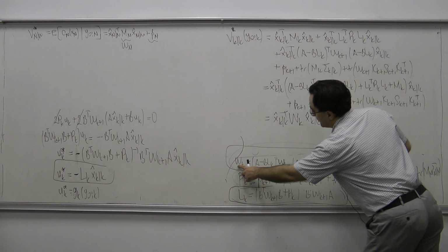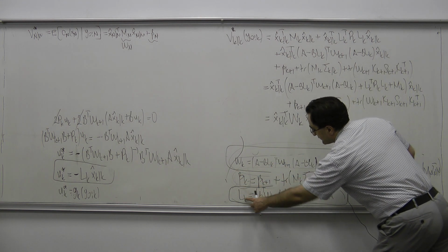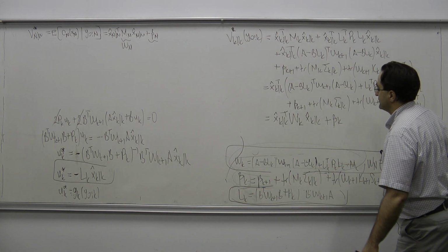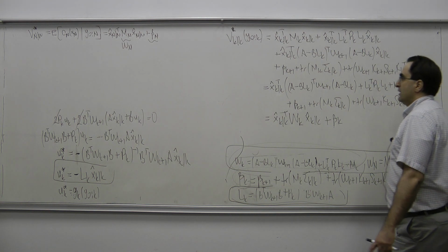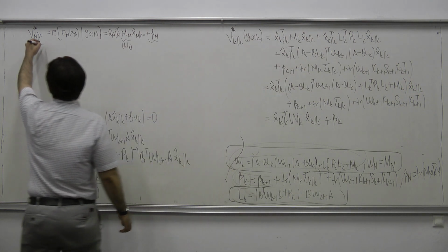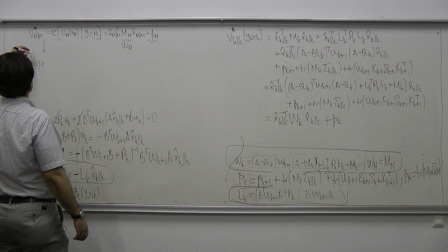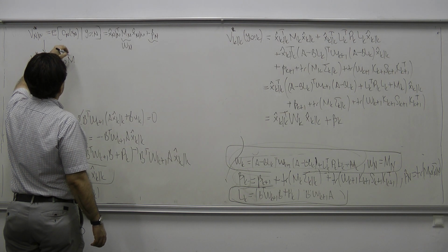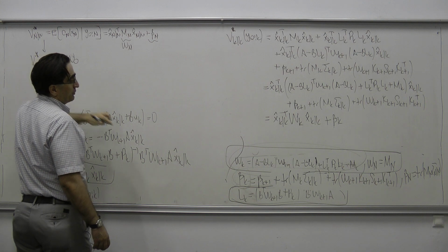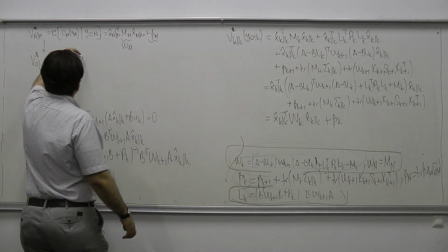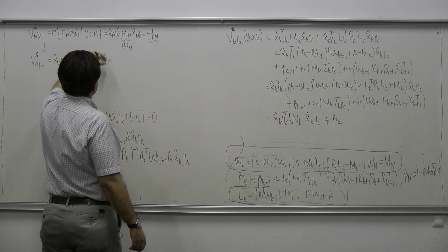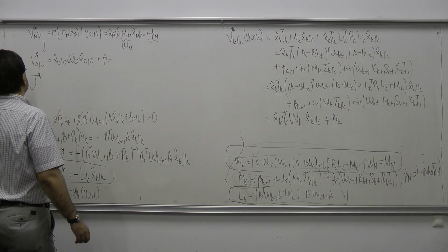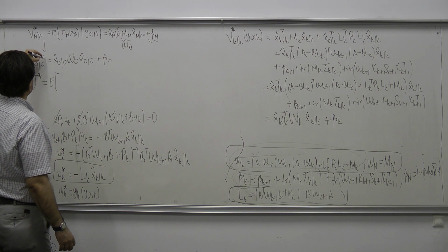And then we calculated Wn minus 2, beta n minus 2. At the same time, I can calculate these control gains, and I can calculate my optimal feedback policies. Then we end up at the end of this recursion at V0 given 0 star, which is equal to x at 0 given 0 transpose W0 x at 0 given 0 plus beta 0.